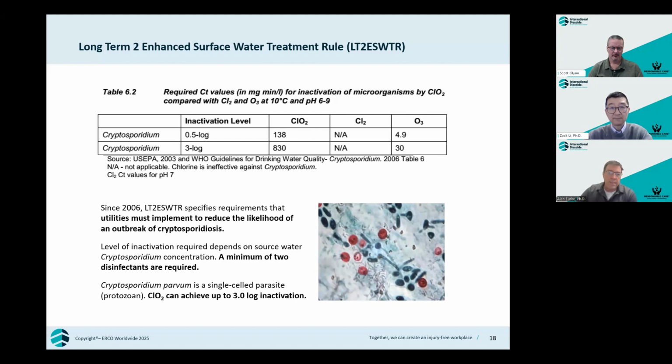In some cases, 3-log inactivation is required if Cryptosporidium is detected at high enough levels in the source water. And in general, a minimum of 2 disinfectants are required if Cryptosporidium is active at any level in the source waters.